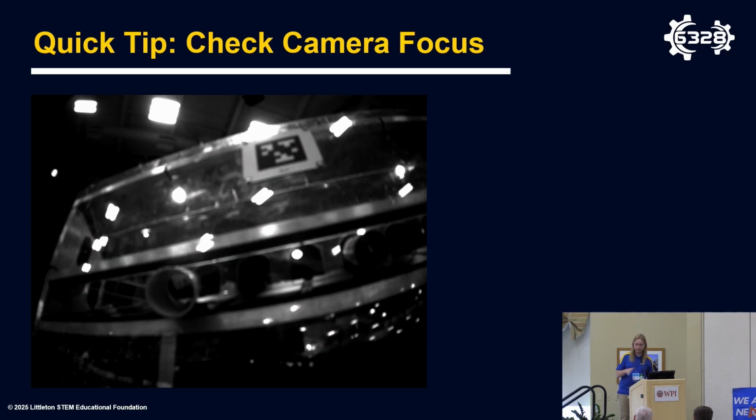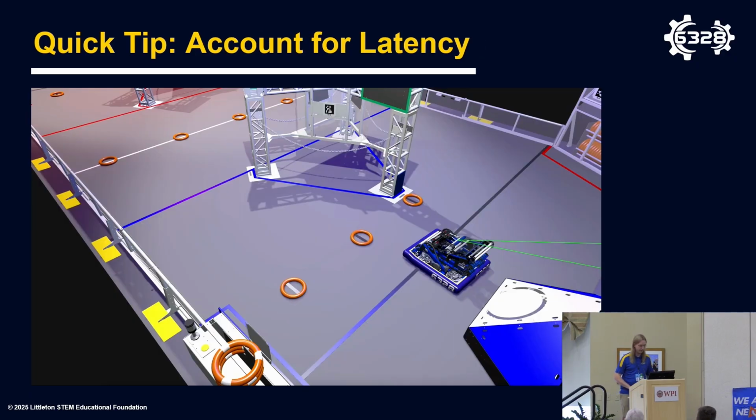Generally, it's also good when you're focusing cameras to bias towards a slightly farther distance if you're trying to do global positioning, because even a tag that is closer, if it's slightly blurry, it's large enough in frame that generally you won't have trouble detecting it. But it's more of a concern at greater distances where you'll lose that detection if you're focused too close.